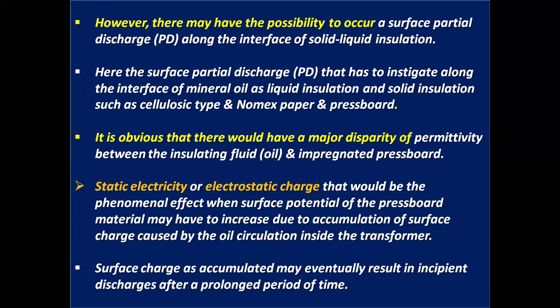Static electricity, or electrostatic charge, is the phenomenal effect when the surface potential of the pressboard material increases due to accumulation of surface charge caused by the oil circulation inside the transformer. Surface charge, as accumulated, may eventually result in incipient discharges after a prolonged period of time.